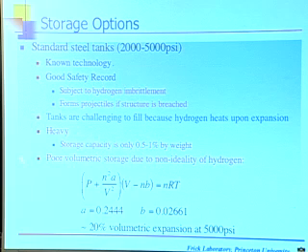You have poor volumetric storage in part because hydrogen, when you get up to the sorts of pressures that you're dealing with, is very non-ideal. That is, the ideal gas law is not a good approximation. You have pretty big numbers for your a and b coefficients in the van der Waals equation. So you're losing something like 20%. If you took the ideal gas law and said, oh, I'll get this much hydrogen under these conditions of pressure and volume, you'd find you're off by 20% in a real-life hydrogen tank at those pressures, a big loss.